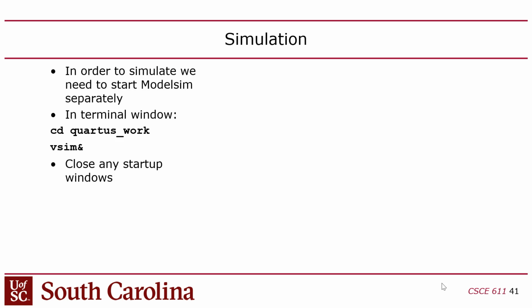It doesn't have the Z or X, which means if you double drive a signal, you won't detect it by running it in Verilator. They do that for performance reasons, I think. Because to implement 4-state logic in C would be very expensive and slow. But the problem is that it doesn't make it really suitable for debugging things. So if you double drive a signal, you may not know it for a while if you're using Verilator.